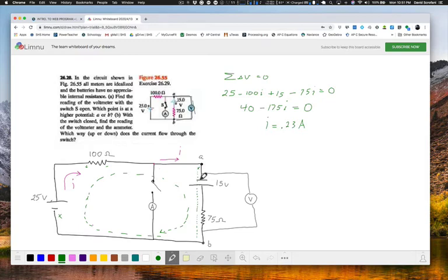So the first thing we find is a rise in voltage of 15 volts. So here, let me just write. This is from A to B. Okay, so we see first a rise of 15 volts, and then followed by a drop of IR. And I'm not making the claim that that's equal to anything in particular, right? It's the equals 0 part that I use here that's Kirchhoff's rule, and that's only true for a loop. So I don't know what this is equal to, but whatever it is, that's what I'm looking for.